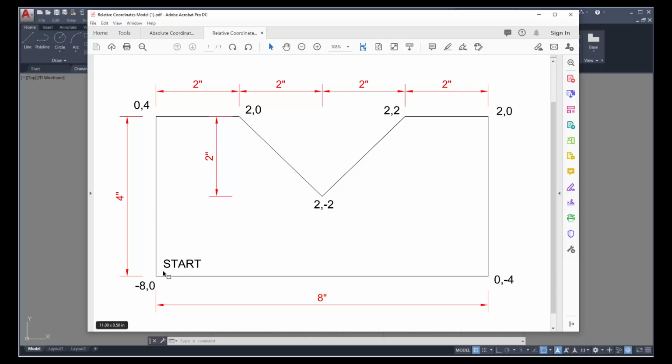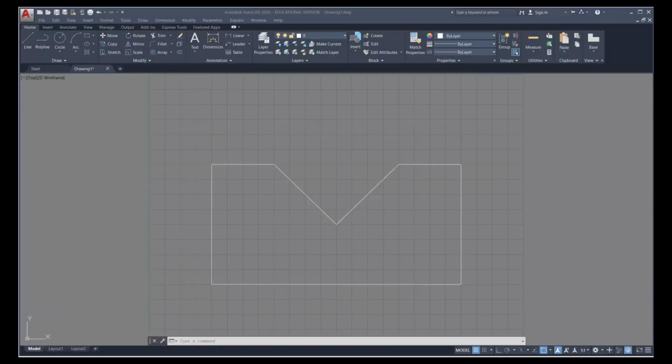So we're going to start at the same point. Now, where was this start point? That start point was 2, 2. That's our initial input. And usually when we want to start a drawing, we're starting from a benchmark, some sort of initial position. If you've received a survey drawing and you want to place your landscape drawing on top of it, you usually want to start your drawing from a known position from the landscape drawing or a benchmark and measure to that using X and Y values to find it. So we're going to do that in a similar fashion, but we're going to start at 2, 2 and then work through the diagram using that type of coordinate system.